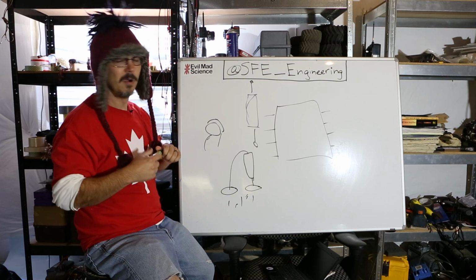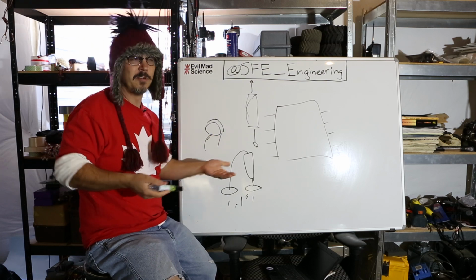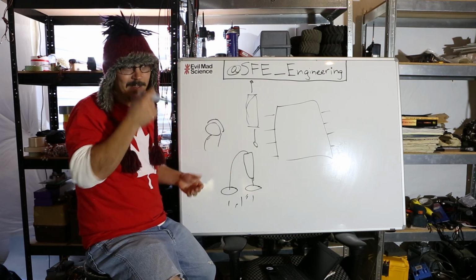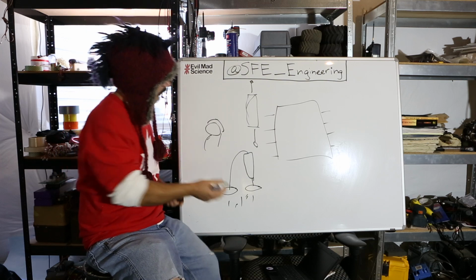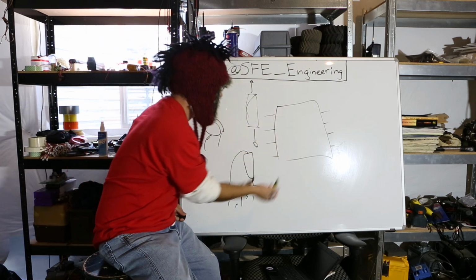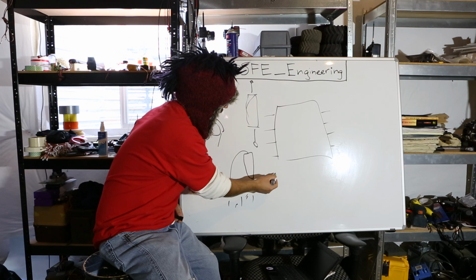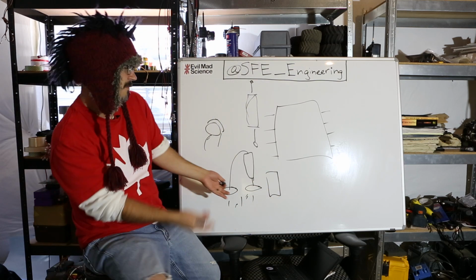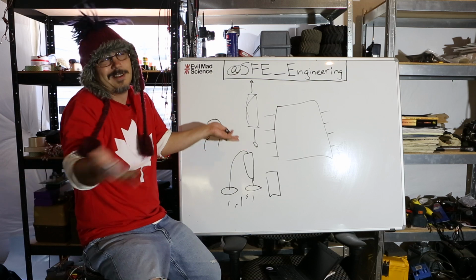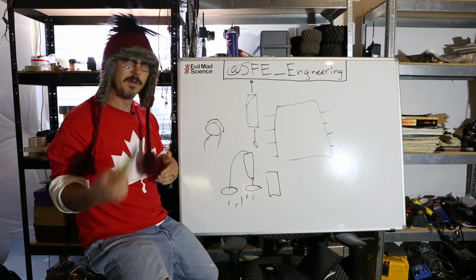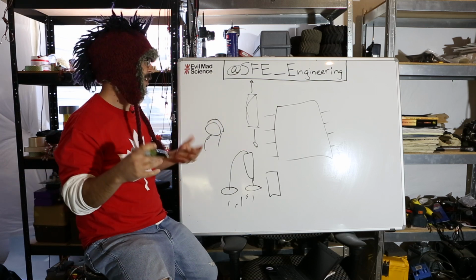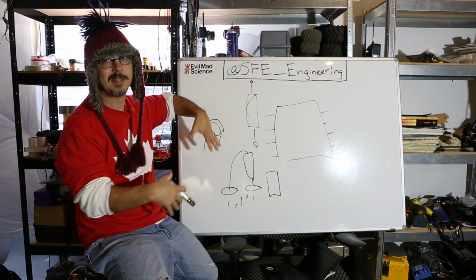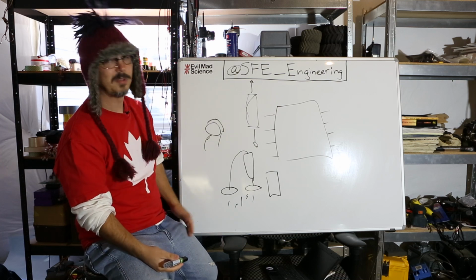So you can go to potentially an 0805 or 1206 or 1210, and those components are pretty big. I mean, if this is our point of reference, an 8-pin DIP, that might be a 1206, you know? I don't know how close I am. Oftentimes, if you can go to a surface mount layout, you're going to save board space, you're going to save your trace lengths. So stick with that as long as you can.